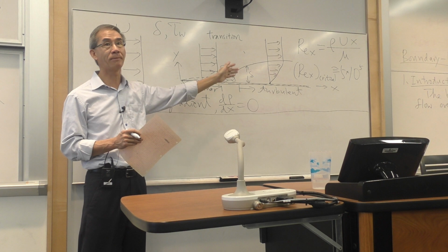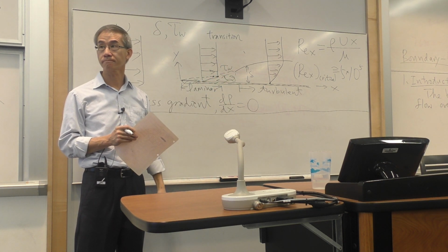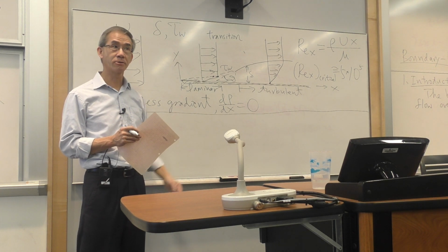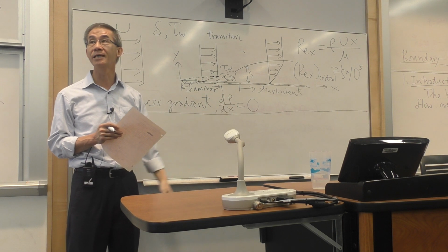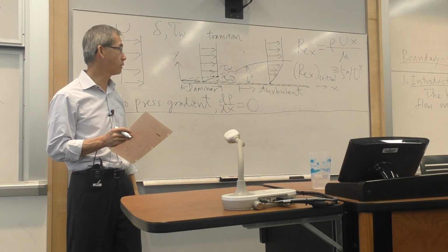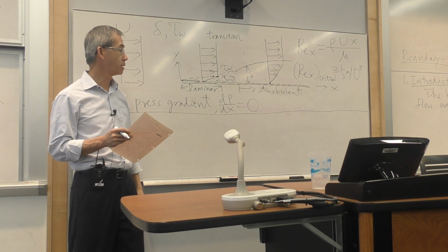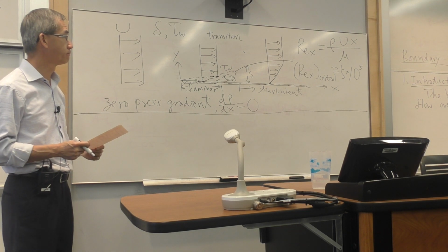Momentum and continuity by itself is all I need to solve for the velocity and the shear. Okay? So unless you're dealing with some energy transfer, like heat transfer, the energy equation is not needed yet. Right? A good question. I think that will give me some idea of how much you understand this concept.